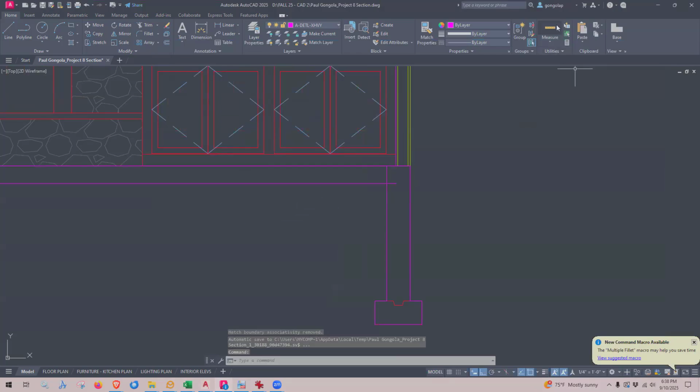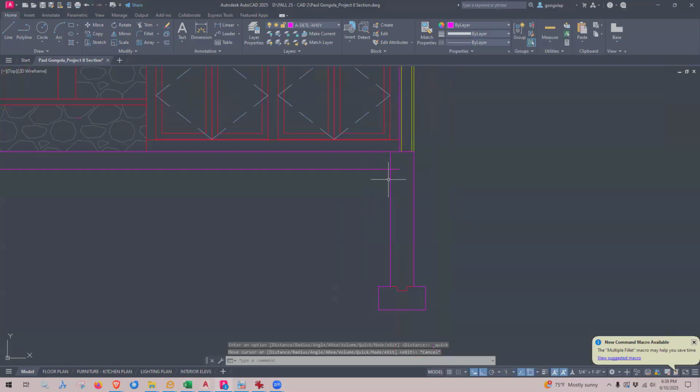There we go. Let me just measure. Yeah, 6 inches. And now I want that little 3x3 chamfer. So chamfer works actually a lot like fillet. The command is chamfer. And when I am chamfering, when I come down here, it's asking for the current chamfer distance. And it looks like I already set mine to 3 inches. Distance 1 equals 3 inches, and distance 2 equals 3 inches.